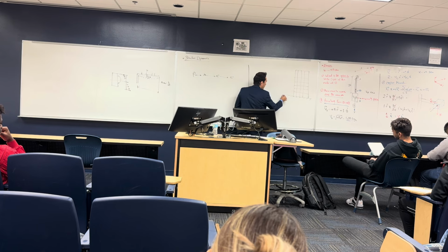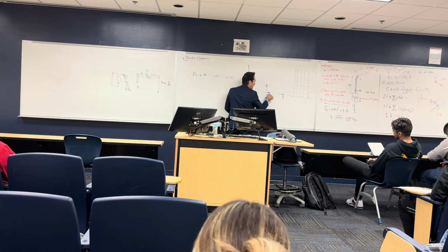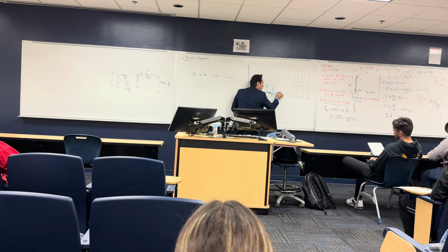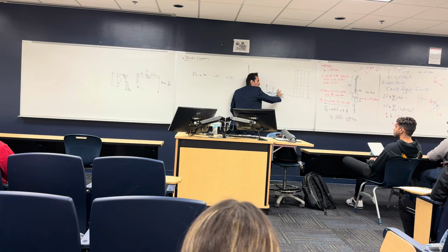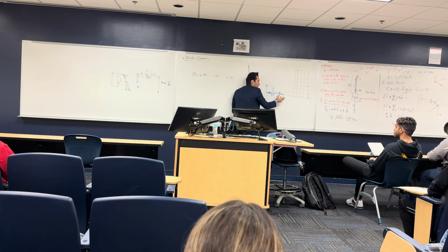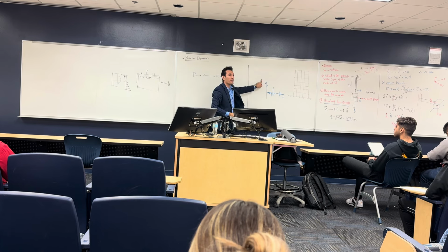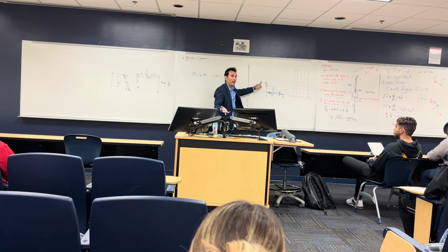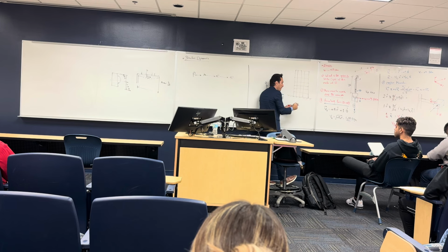This is the ground, and this is the time, and this is the force of the earthquake. It's very, very small at first, then keeps increasing, and then it has a very high shock, and then it dies out, and maybe there are some aftershocks, and then it dies out. So this is the main shock, and this is the aftershock. Some earthquakes don't come with aftershocks. Okay? So this is time versus acceleration, and we call this the ground acceleration. If you have the ground acceleration, you can get the force of the earthquake. You multiply mass by the ground acceleration, and you get how much force this building is absorbing.